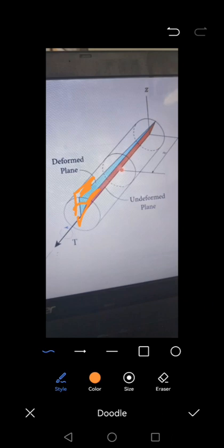That angle is very important, because if you exceed the safe angle, then this shaft is going to break. Therefore, they will give you the angle and say that the angle of your shaft must not exceed a certain value. So when you apply torque, you must make sure that the torque you apply is not going to cause an angle bigger than the given angle. So this angle of twist,